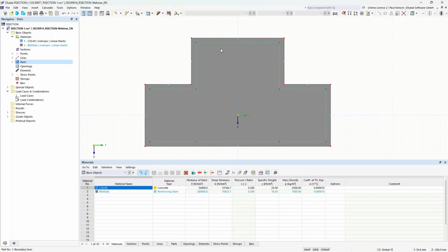If you have entered such a section, then you can also modify it. For example, you can go into these options, and in this toolbox, you find an opening, for example, a rectangle opening. And if you would apply this one, then the program would automatically generate this concrete covering line for this opening. That would be the way for the rectangle opening.